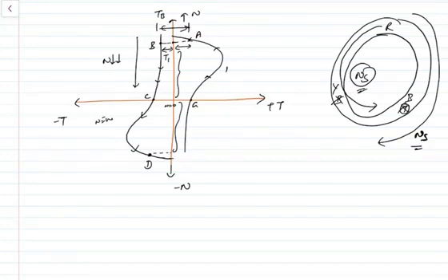So if you want to stop your motor, you have to disconnect your supply and apply the mechanical brakes when it reaches point number C. Otherwise, it will accelerate in the opposite direction. It will reach a stable point in the opposite direction.